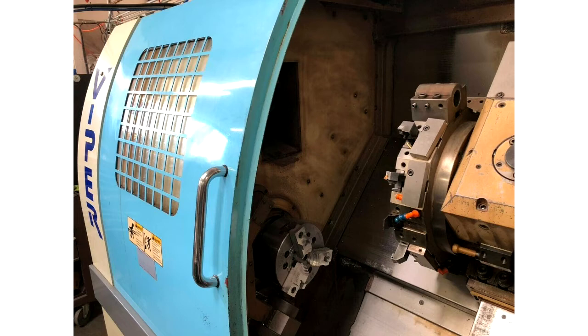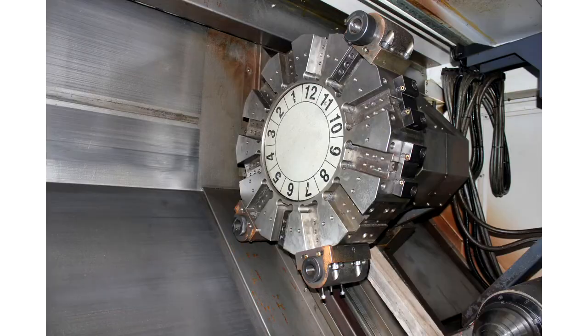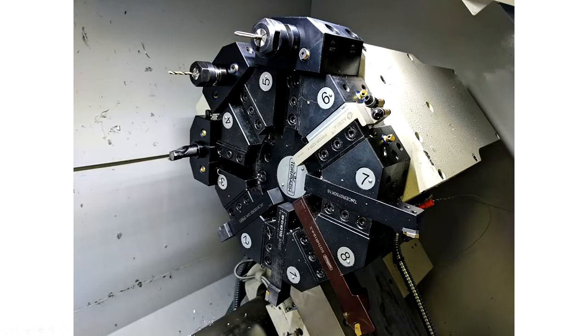So if we look at another angle, this is the front of the turret, and this one's empty. It doesn't have any tools, and we have 12 positions on this particular machine. And so that's what we're going to model our assignment around. You're going to figure out which tools are going to go in which position and build your tool library for HSM. Don't worry, I am going to give you lots of help here.